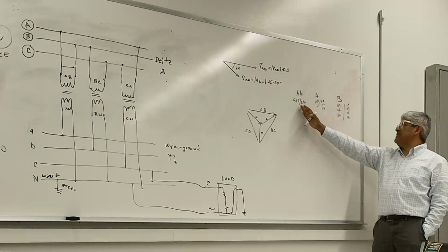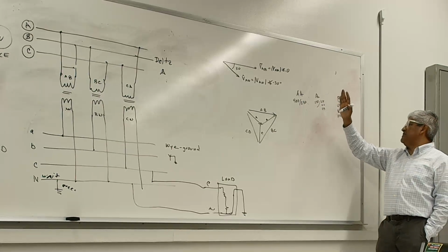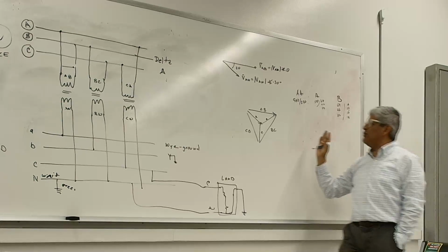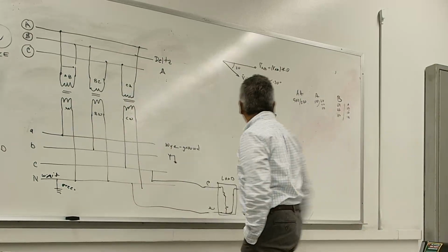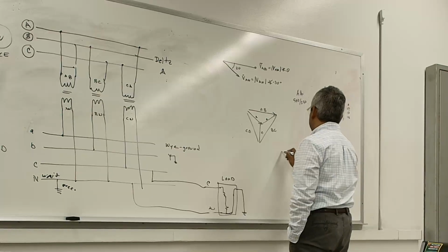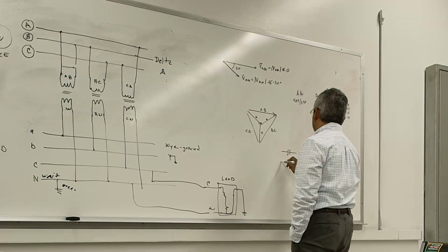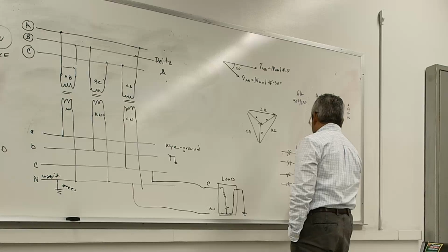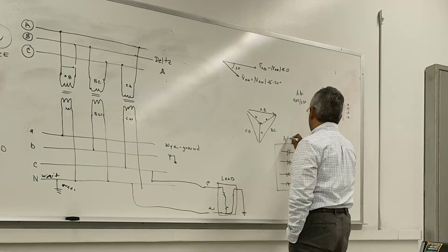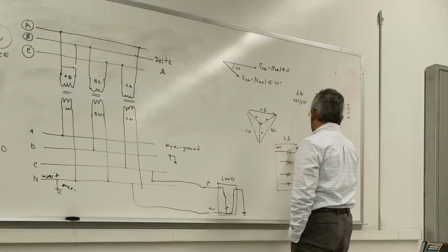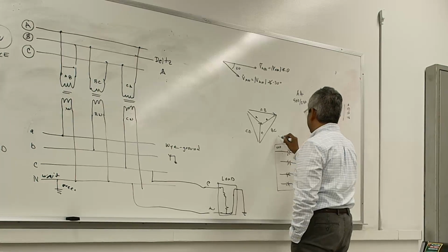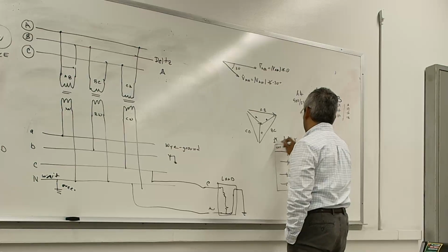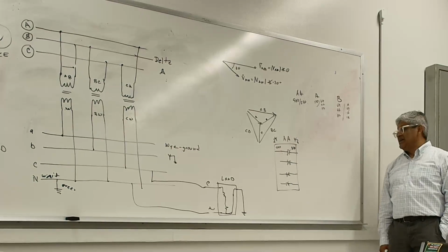So they call this double A station, they call this A stations and B station. How does that come into play here? Okay, this is how it is. So you have an A station. I'm going to use the maximum number of transformers that they will have. They're all three phases, by the way. Okay? So this is what we call a double A station. 500 on this side, 230 on this side. These are wye grounded transformers.